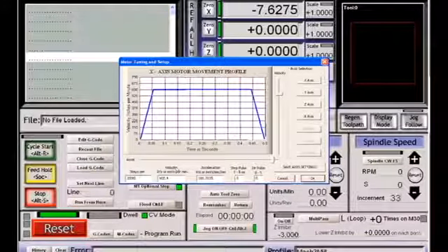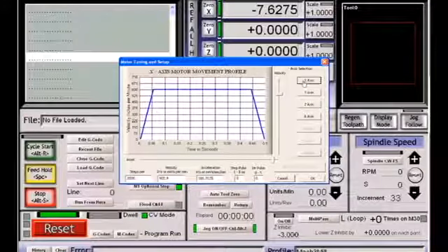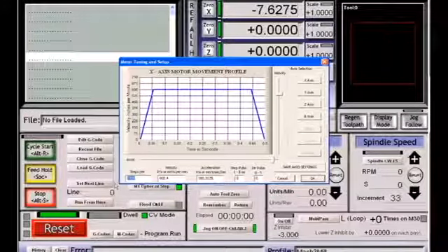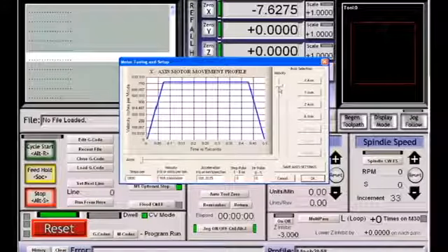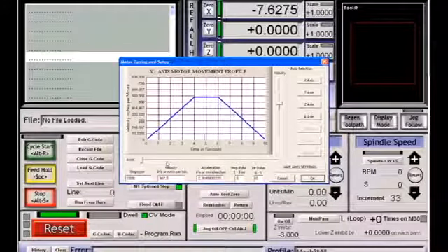start. Once you've set a steps per millimeter of 2,000, you need to test to see what acceleration and what velocity you're going to use. I should mention that before you start anything on this tab, hit the axis button that you're interested in. It brings up the stored results of that axis. So here we have the x-axis. We're going to set this as an example for the user to 1800 steps per millimeter. Anytime we change this steps per unit, we must touch the velocity and touch the acceleration sliders so that the system will recalculate its current settings based on its steps per unit.